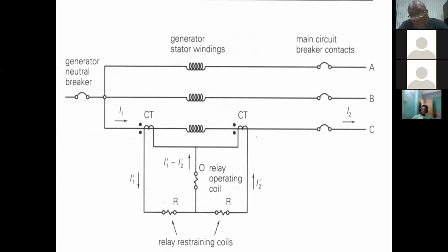What that means is that the fault is not on the unit that is being protected by the differential relay. But the fault current is passing through that protected device. Make sense? Since we know that the fault current originates from the generator, it may be a little difficult to think it through. Let's use a transformer. The transformer is connecting systems of different voltages, right? That's what it does.